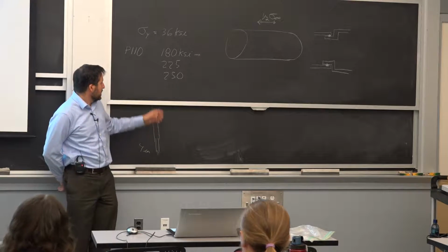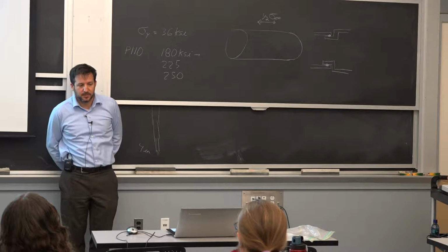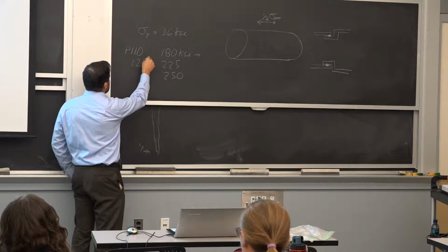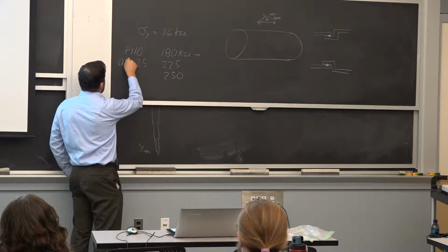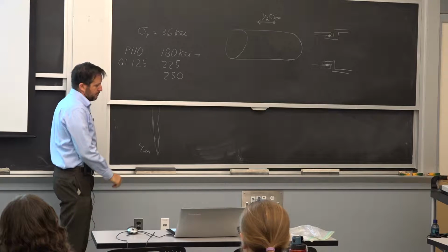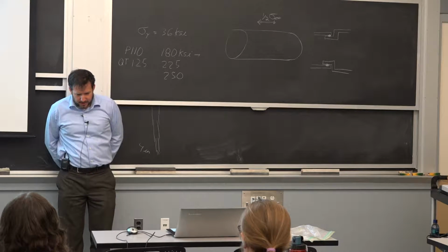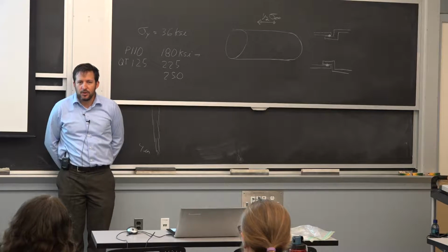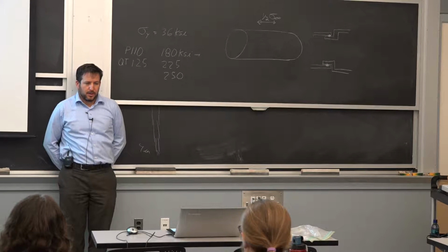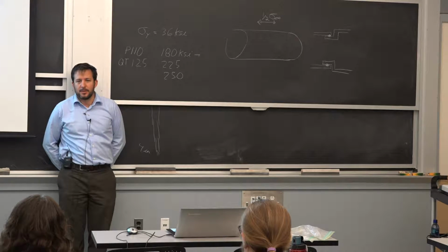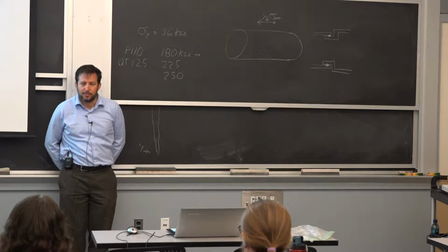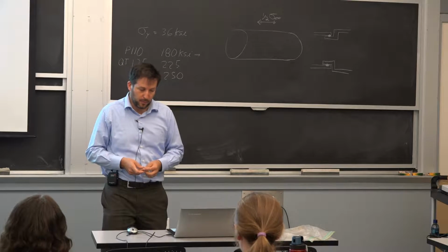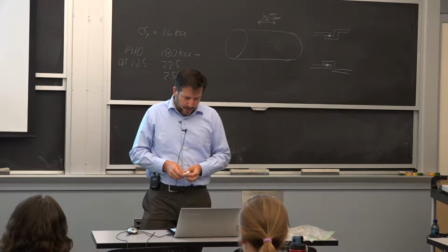We're still talking about the same kind of strength in general. P110 is very critical. I have a project where they were using 125 strength, quench and tempered 125. It didn't fail at a joint. It doesn't seem to be related to the heat treatment, but it did fail. We're trying to figure it out, even though there's consequential damage from the failure, and sometimes it's difficult to differentiate between the two of them.